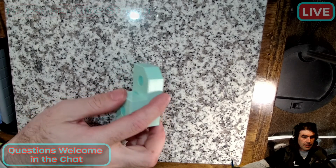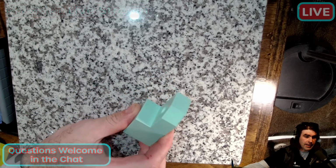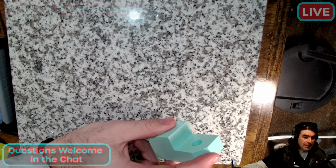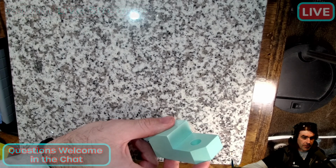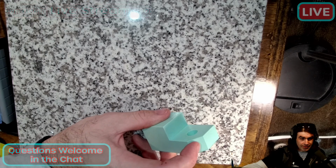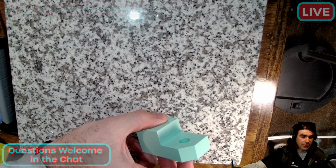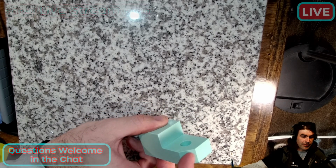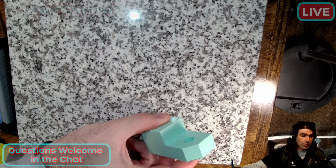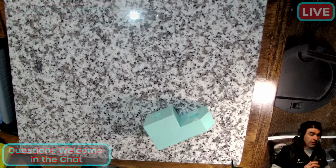I'm going to put it on the plate and rotate it up by use of a sine bar, which I don't have handy, and check it just like parallelism. It's not the only way to do it, but that's the best way I can think of. You set a sine bar to 30 degrees, and now this surface is nominally parallel to the granite plate, so we can run an indicator and test it just like parallelism.